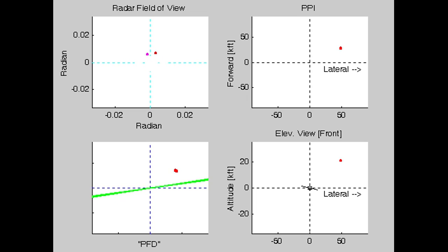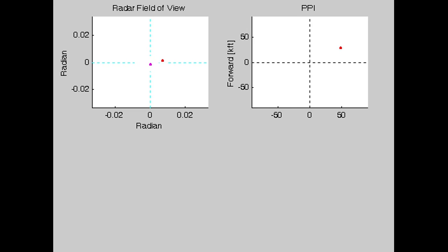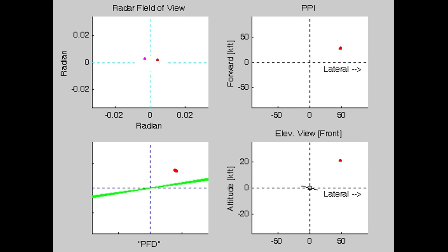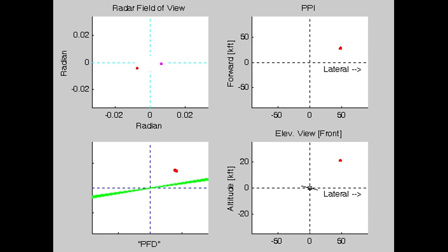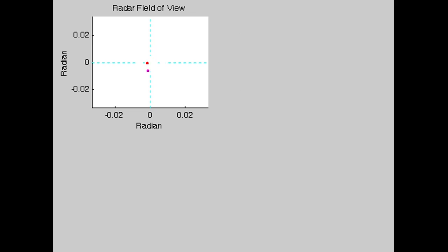point as intended. That's symbolized by a magenta-colored dot, and the total error, with or without compensation, is represented by a red-colored dot. Each dot was generated from a random Gaussian sequence of independent values with zero mean and standard deviation at 0.3 of a degree. For this case being shown here now, antenna pointing error was compensated, so the magenta-colored dot value didn't contribute anything to the position of the red dot.